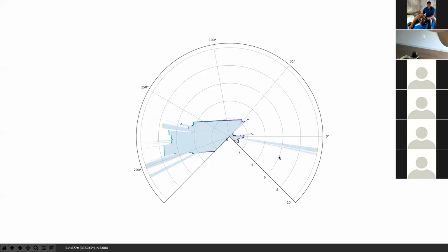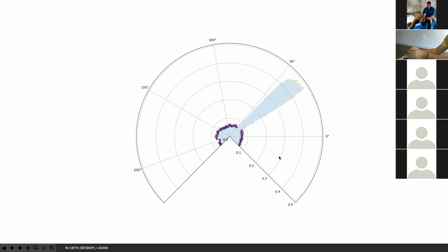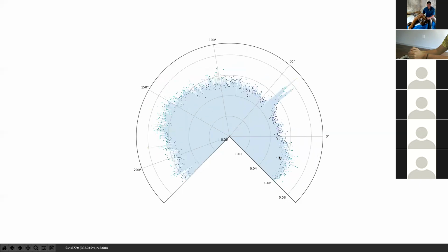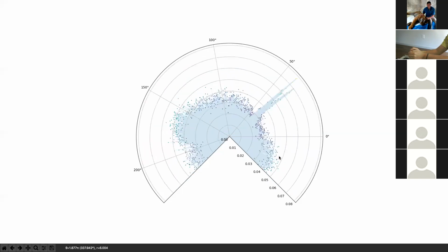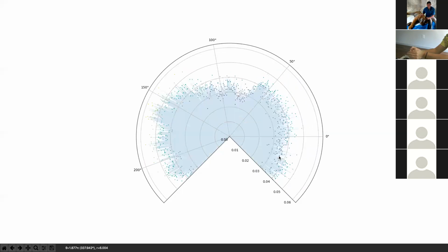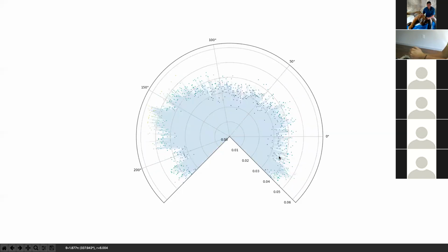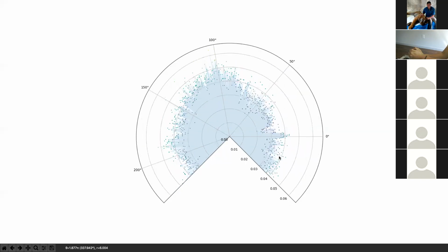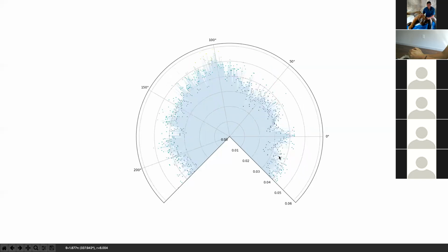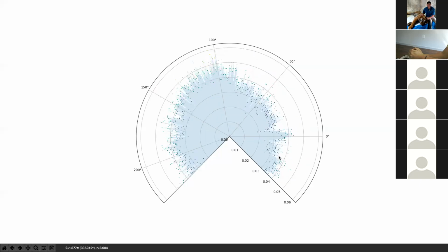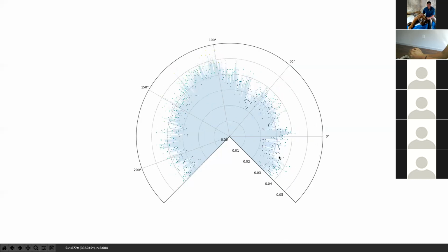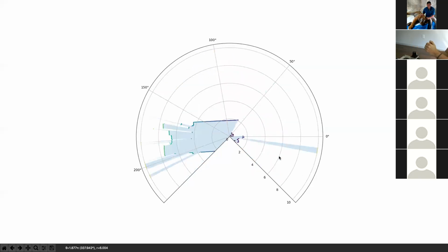Yeah, so an interesting thing you could see is when Jorge cups his hands around the LiDAR, you can see the individual points, because this LiDAR has, if I remember correctly, a 2 centimeter resolution. So any distance value that it returns has an accuracy of plus or minus 2 centimeters. And here you can see, as he cups his hand around the LiDAR, it's measuring the points that are very close to it. And it doesn't return 0, it returns about 3 centimeters, because if you were to look at the LiDAR,